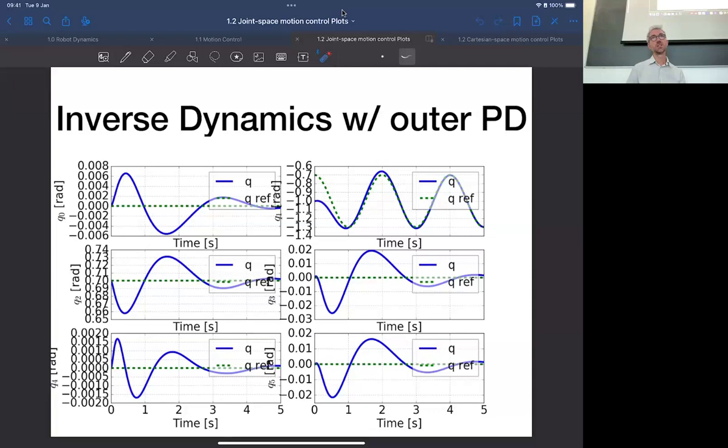We are operating on discrete time instead of continuous time. Yeah, that's a big assumption that we didn't really discuss so far. All the theory we have seen so far, and actually most of the theory we're going to see in the coming lectures, is for continuous time control, which means you assume that your controller is operating in continuous time. In practice, what you have in real robots is that the controller is operating in discrete time.